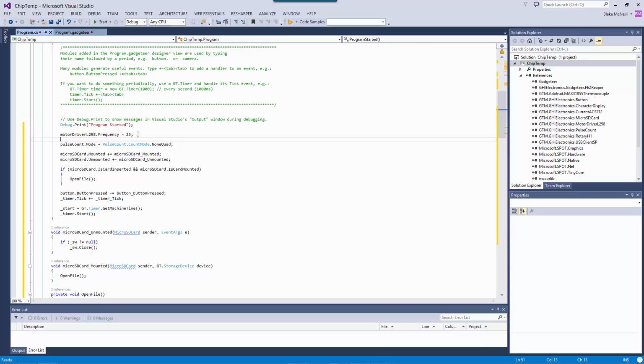Now, I'm going to do this experiment again later because it's posed some questions for me. At different frequencies, does the motor set up ripple currents or whatever? Can we heat the motor up by improperly selecting frequencies that don't work? I know that you can make motors sing by setting up harmonics in them with different frequencies, and those sounds are just annoying as heck. So you try and pick something that's not going to create a harmonic within the motor and cause this buzz. So after I'm done with this experiment, I'll probably go and play with changing my frequencies.